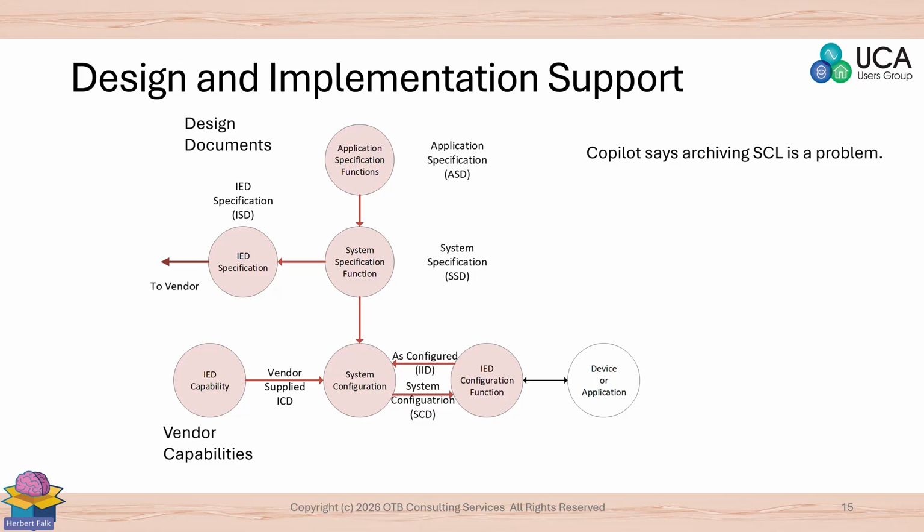Devices are required to have what's called an IED capability description file, which then gives their capabilities to the system configurator, which outputs a system configuration description file, which goes to the IED configuration function and configures the device. And if there are changes made, that information can be fed back to the system configuration tool.